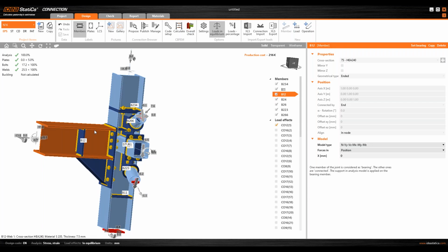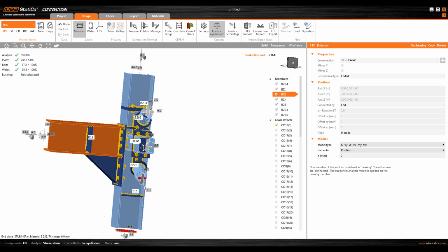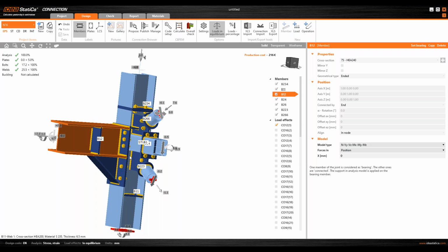So one thing is cross sections don't have to be the same. The other thing is that there are also tolerances in the angle or vectors of the members. So if this member was, let's say, tilted by 5 degrees, I could also use the template. I hope that's clear. So the geometry doesn't have to be exactly the same, but there are some slight tolerances. Yeah. Okay. Perfect. Good. Thank you.